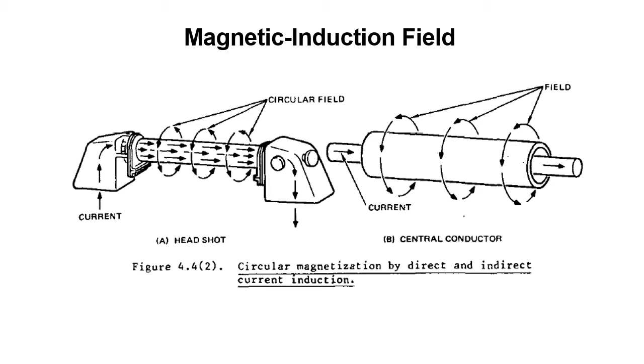Usually with magnetic particle, setups for more than one direction must be made to ensure that all discontinuities will be seen. In some cases, the current may flow through the part. In other cases, separate conductors or coils will be used, just depending on what you've got going on.